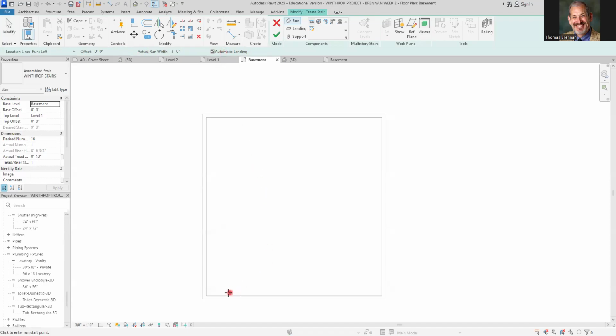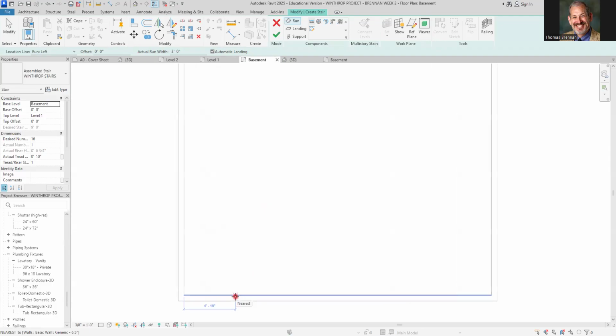I'm going to start by putting it right here. I'm going to back it off about 3 feet away from here, and then go a little bit further, about 5 feet. Watch what I do. You see it says 5 feet, and it's finding the wall. So I click right there and pull on here. Now see what it does? It's creating these. If I keep going this way, it'll run it in this way, which I don't want. So I just bring it over here until I see 2 risers, which is what you see there. When you see 2 risers, you click.